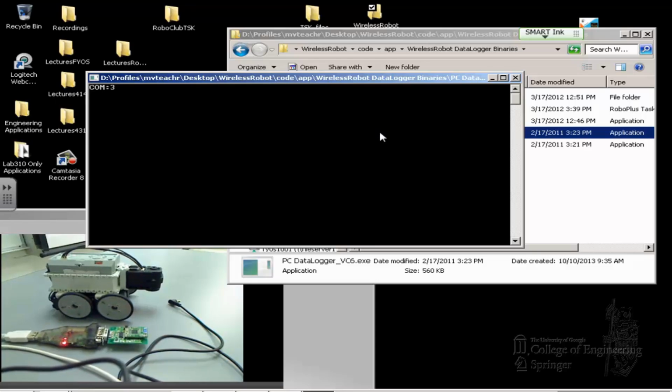So you push 3 because that's COM port 3. Hit enter. If it responds with COM3, which I'll explain later when I explain the main code, that means it has actually found COM3. There's a real device there, and it's talking to it. In the main program, you have different code to handle if somebody enters the wrong COM port. So if you see this, we are okay.